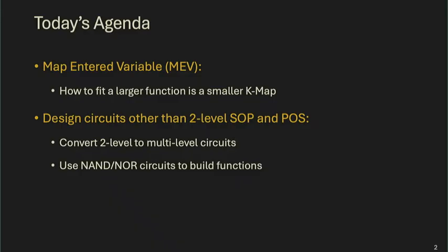We talked about K-map, which works pretty well for 4 variables. It's a big mess for anything more than 4 variables. We talked about the Quine-McCluskey algorithm, which can work with any number of variables, but it's also a lot of calculation. You need to deal with so many binary numbers, do all the combination, tabulation, prime implicant charts, go through multiple steps to find minimal cover.